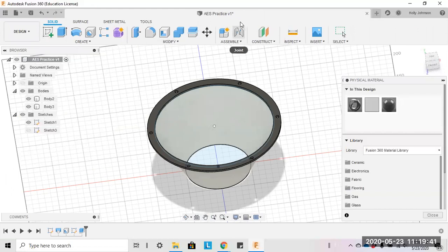Also with assemblies, usually they're called mates. Here they call them joints. So that's almost like constraints within the sketch realm. Within the assemblies, you generally have mates between objects. And so that could be, oh, I want to make sure that this surface sits on this surface, or if you have a bolt, let's say, I want the outside of this bolt to line up with the inside of this hole, and I want it to be this deep in the hole.